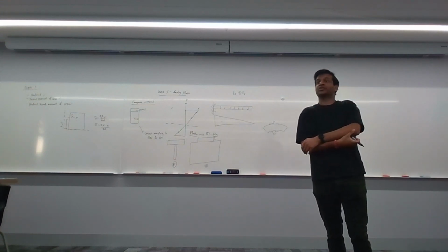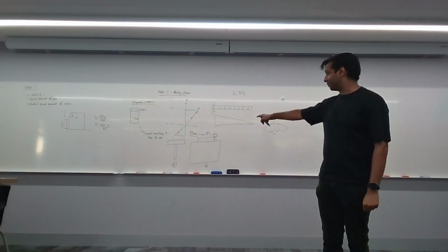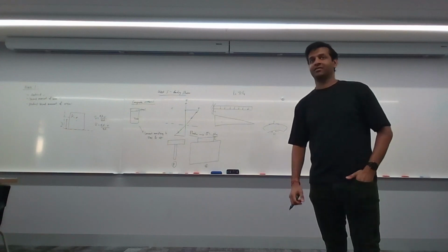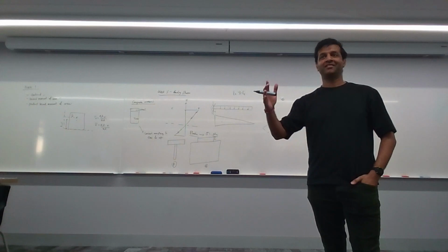So if you've got a steel plate on the top and the rest of your cross section is timber on the bottom, and the question asks you to convert everything to steel, what would my transformed cross section look like? Would it be scenario A or scenario B? A? A? Anyone says B?